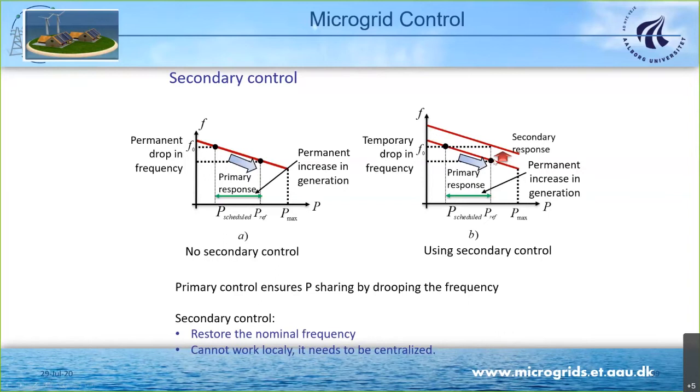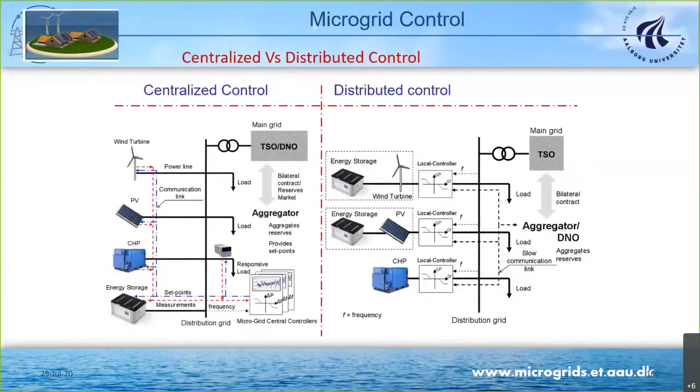So those are coupled, right? So if I inject more power, automatically I will shift up the frequency. This kind of controllers I can embed in a single, let's say, centralized controller. So like a SCADA system, measuring frequency and voltage, and then sending the setting points to each of my devices in my microgrid. Or I could use also local controllers sharing information and try to decide things. So we have both ideas here.